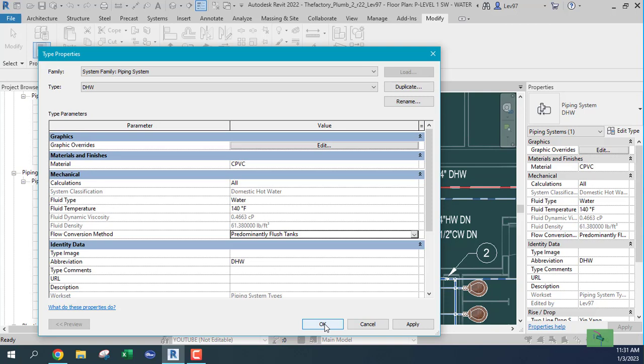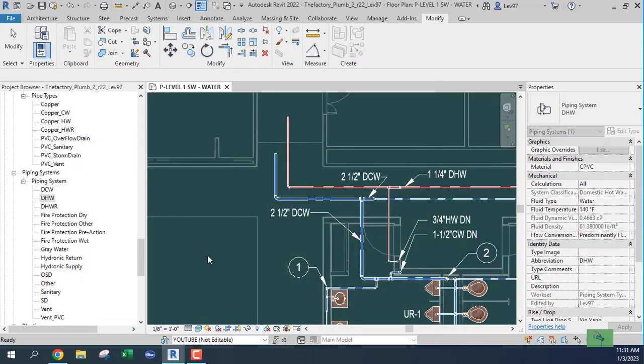So you want to keep that, especially if you're on the lower end of the curve. Looks like on the high end, it doesn't matter, well, no, it does matter, because at 225 fixture units for flush tanks, you get 70 GPM, and for 225 cold water fixture units, you get 97 GPM. So there's a big difference. So you might want to watch out for that.